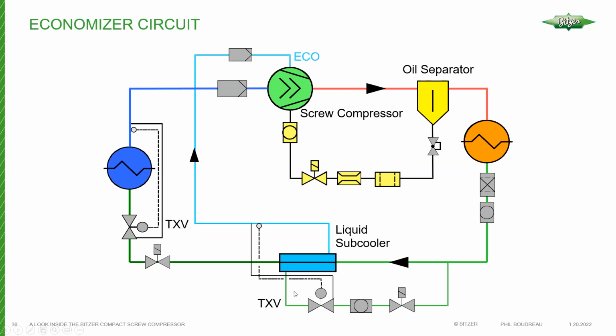So it looks like this. Okay, so we have our screw compressor. Discharge gas, I'll just start at the high side of the screw compressor. And actually the graphic is kind of showing a semi-hermetic compressor. With the compact screw, just keep in mind the oil separator is incorporated with the compression process here. This is all a compact screw compressor here. There is no external injection line. This is just a graphic that I pulled from a semi-hermetic presentation that I had,